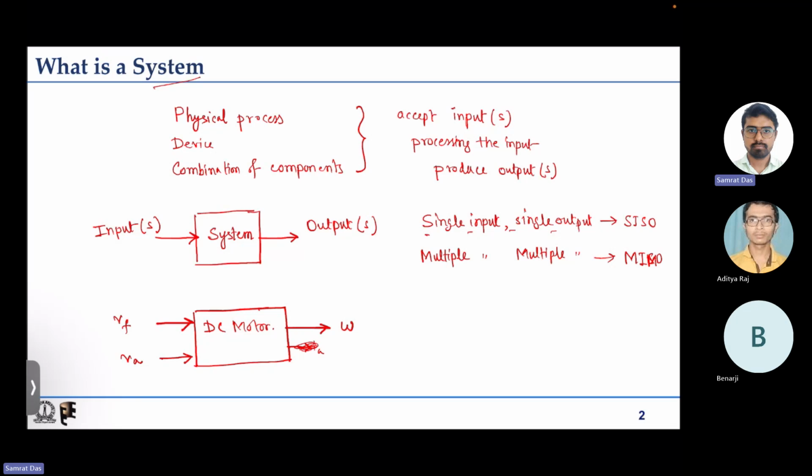Now the next discussion that I was starting is, when you are operating a DC motor, unless we are going to operate the motor with field weakening, that is when we want the motor to rotate at higher speeds compared to its rated operating speed, then we would need to weaken the field. We would need to reduce the field voltage and thus reduce the field current.